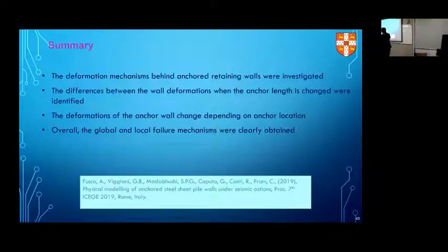Now the application for you is that if you are going to use new materials behind to do the backfill, say you want to strengthen the soil behind, how is it going to behave even under an earthquake loading? You can do these kind of tests, and you don't need to produce thousands and thousands of cubic meters of material to do a field test, whereas if you give us something like say 20-30 kilograms, that should be enough material for us to do tests like this. Okay, so that's one application.